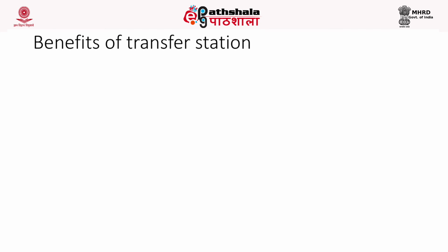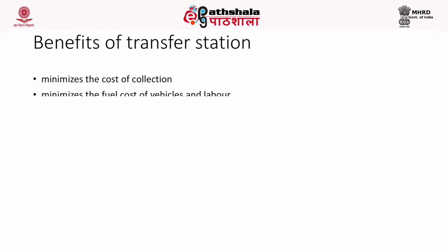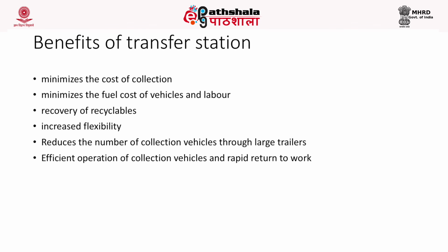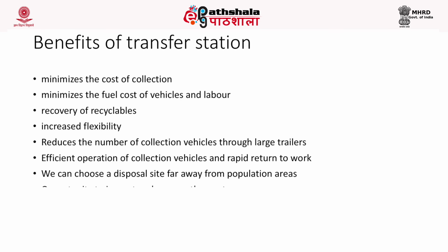Now let's look into the benefits of transfer station. The benefits of transfer station would be to minimize the cost of collection, and minimize the fuel cost of vehicles and labor. Also, it helps in recovery of recyclables. It provides a lot of increased flexibility. It reduces the number of collection vehicles through large trailers, and also allows efficient operation of collection vehicles and rapid return to work. We can choose a disposal site far away from population areas when we have a transfer station installed in between the collection and the disposal site. Also, they provide an opportunity to inspect and process the waste.